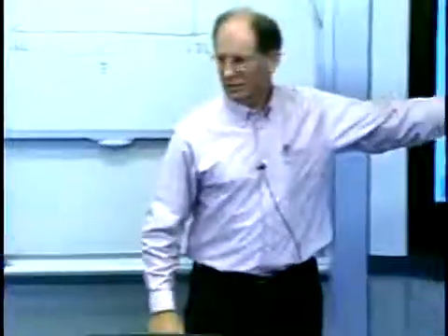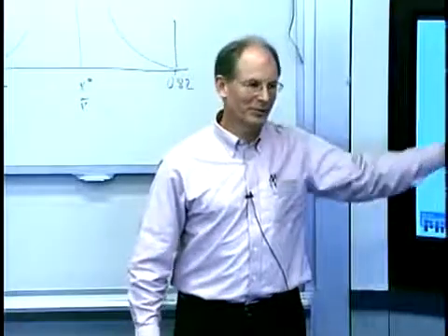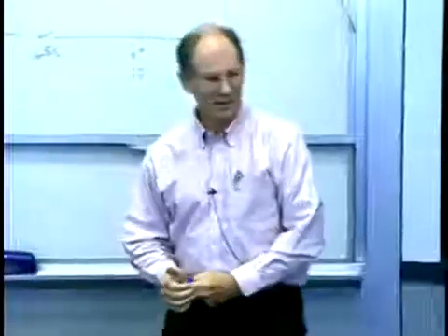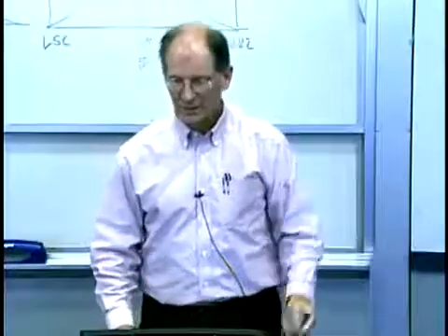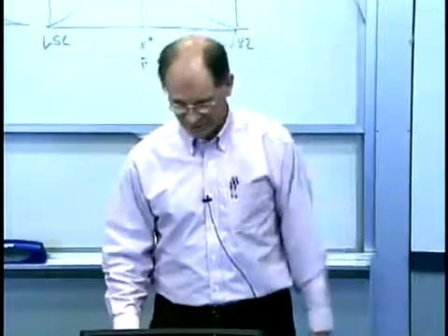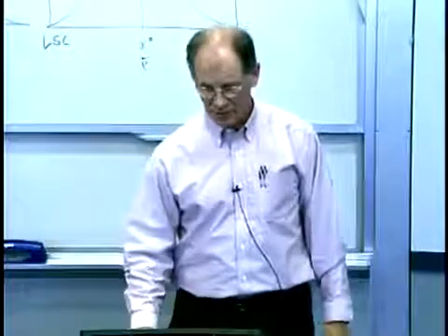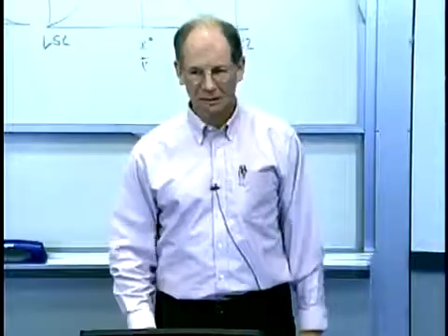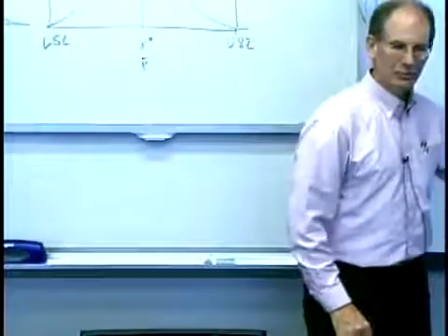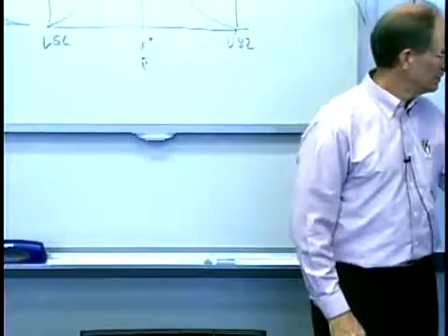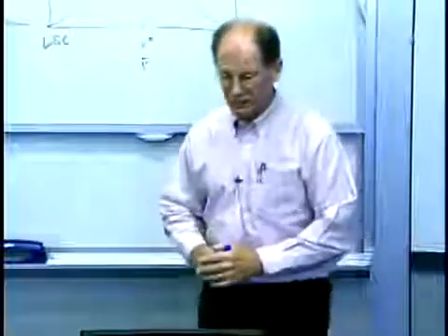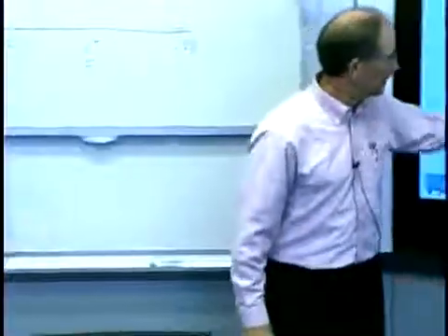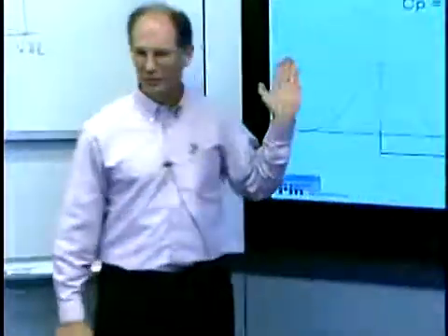So yeah, CP of 1 is not particularly that good. Okay, companies like to have it a lot higher than that. Here's an interesting one. Look at the difference between this. CP is 1, CPK is 1. CP is still 1 because the width of this distribution didn't change. But the mean shift was such that I actually have half my parts will now be bad.